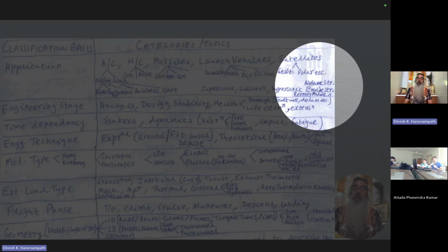Finally, in terms of a re-entry module, when essentially the vehicle is supposed to be reused and therefore comes back to Earth, it faces a very large thermal load on re-entry, because it is going through the atmosphere at a very high speed. The thermal loads that get generated are so severe that the re-entry module structural analysis is very different. Of course, you'll have a lot of active cooling and also tile structures, ceramic tiles, etc., and how they're going to be transferring the load between them and what kinds of failure could occur over there are very different from what we consider with typical airframe structures like just a wing or a tail.